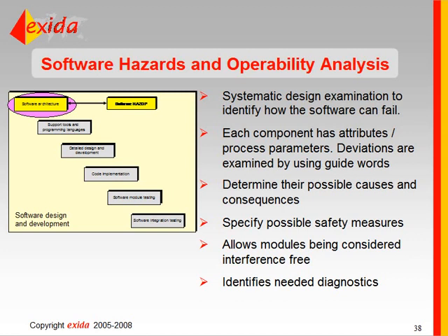If you've done this type of failure analysis on software modules and have shown that a particular module cannot cause any of the safety functions to fail, then that module can be considered interference-free, and it does not have to have the same rigorous process followed in its development. And this will also identify diagnostics that you need on the software itself.